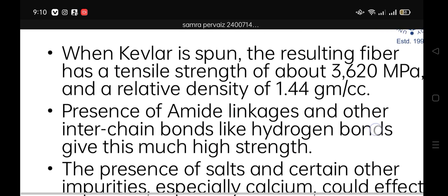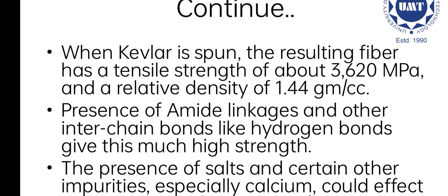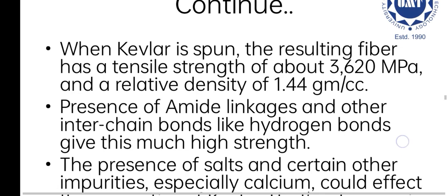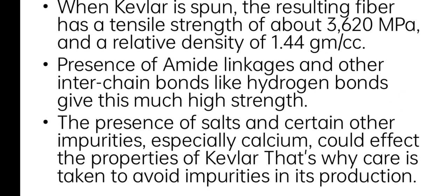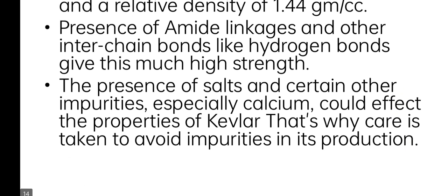Presence of a mild linkage and other interchain bonds like hydrogen bonds give this much high strength. The presence of salts and certain other impurities, especially calcium, would affect the properties of Kevlar. That's why care is taken to avoid impurities in its production.